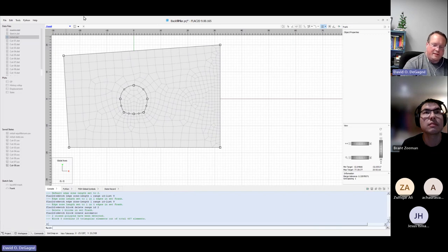It could help if you have big displacements and large strain. Larger zones are going to start to get twisted and not work sooner. So the finer you make it, the longer you delay that. But if you're getting into that situation in this case, then you just don't have a strong enough backfill.